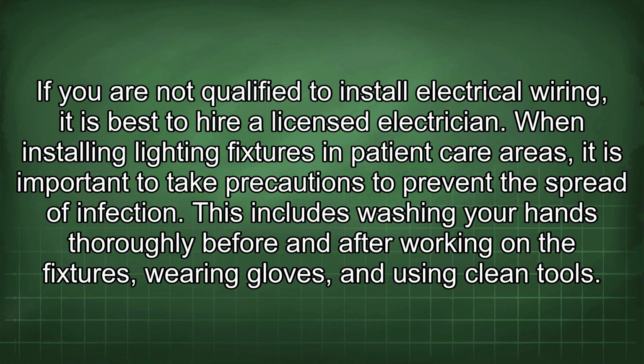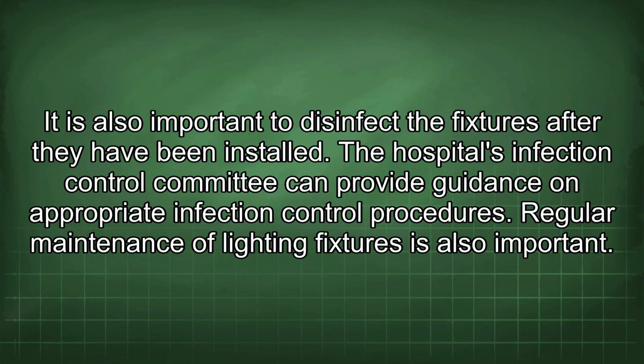When installing lighting fixtures in patient care areas, it is important to take precautions to prevent the spread of infection. This includes washing your hands thoroughly before and after working on the fixtures, wearing gloves, and using clean tools. It is also important to disinfect the fixtures after they have been installed. The hospital's Infection Control Committee can provide guidance on appropriate infection control procedures.